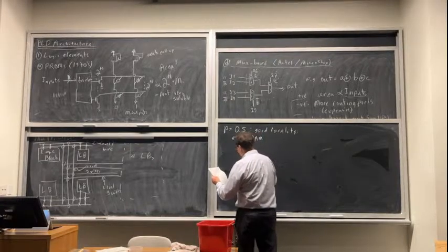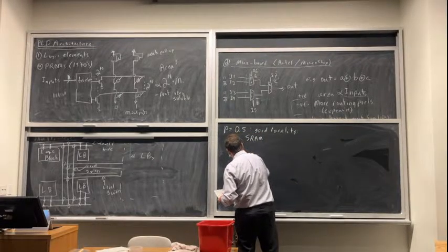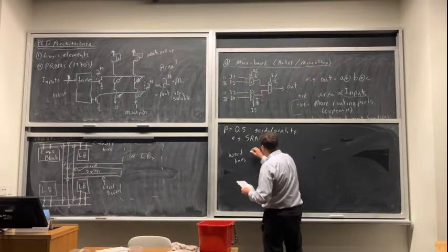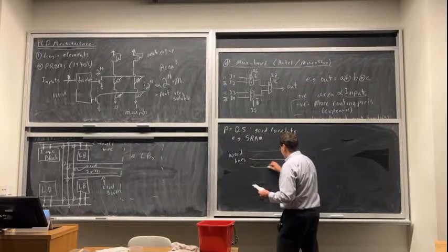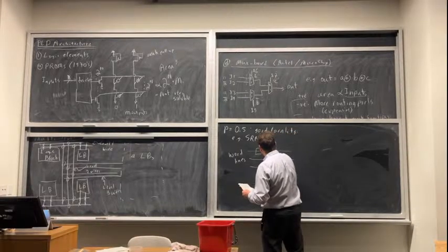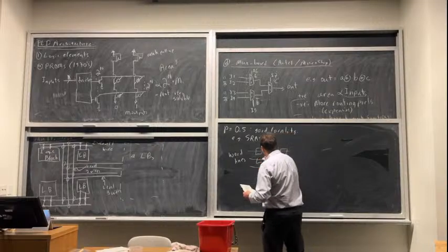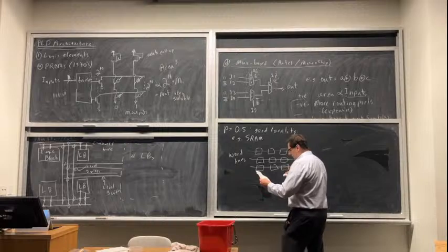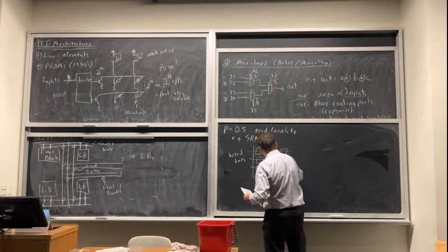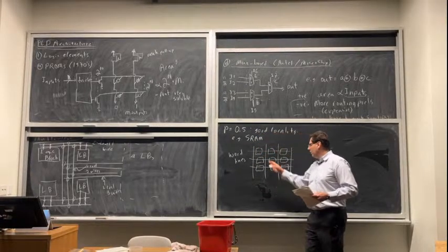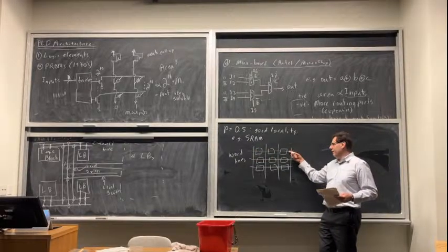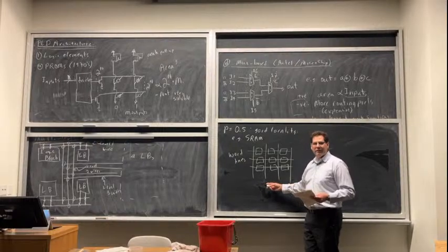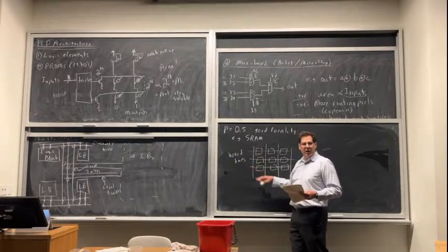So if I build an SRAM, you have word lines here. So this is like the SRAM core. You have word lines, and those word lines go across and they select a bunch of SRAM cells. So I have SRAM cells under these, and so on. And then I have bit lines between them. Okay, so you activate the word lines. One set of these is activated. They start pulling apart the bit lines beside them, and you read out your outputs here. So your inputs to this array is basically number of word lines plus number of bit lines.